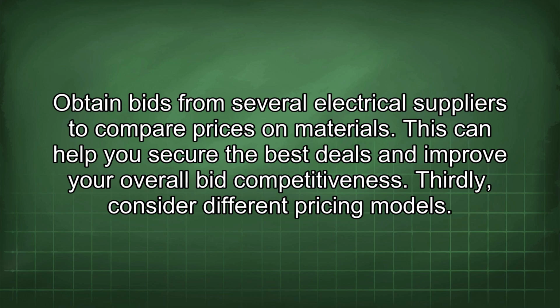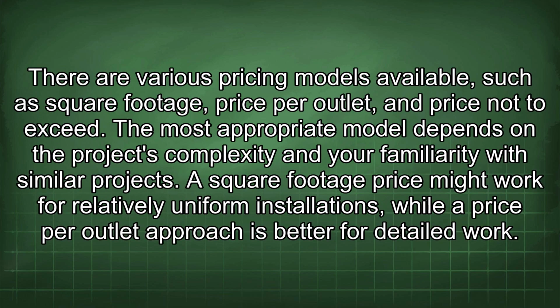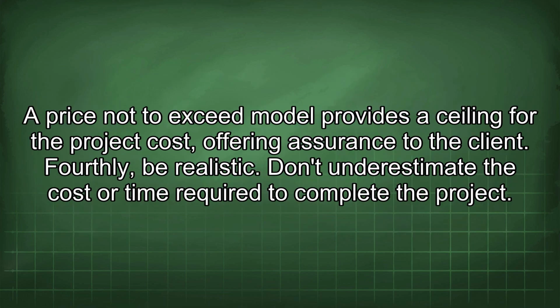Thirdly, consider different pricing models. There are various pricing models available, such as square footage, price per outlet, and price not to exceed. The most appropriate model depends on the project's complexity and your familiarity with similar projects. A square footage price might work for relatively uniform installations, while a price per outlet approach is better for detailed work. A price not to exceed model provides a ceiling for the project cost, offering assurance to the client.